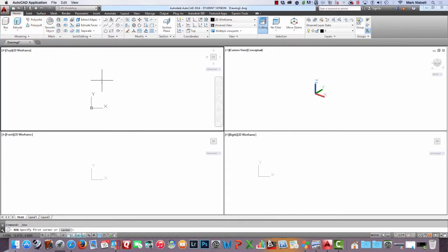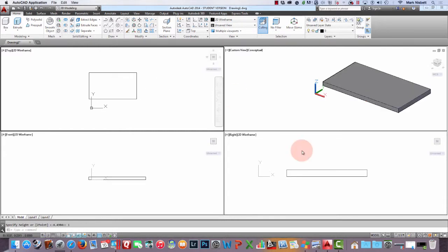So anyway, let's start off with a simple box. Basically, it's very easy to do. You just click the corners as if you were drawing a rectangle, and then it asks for a height, and we just give it a height of, say, 1, and there's our first 3D object. So we don't have to do an extrusion because we're doing a routine that draws a box for us. It draws a rectangle and extrudes it a height. That's as simple as that gets.